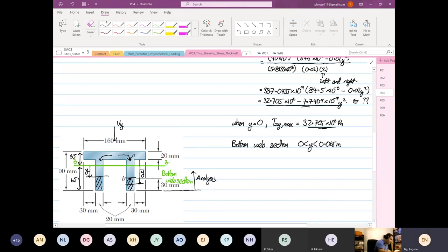From here, that's where things get a bit confusing. Some of you may say, hey Eugene, the shear force is from the flange coming down, why do you now ignore it? We have to obey the rule that the analysis will start from y max, and it cannot cross the centroid. This is because the problem comes with the first moment of area.